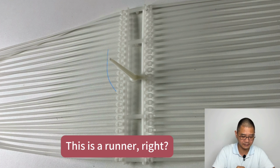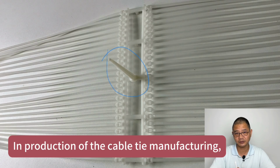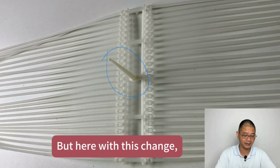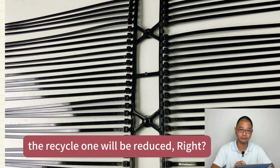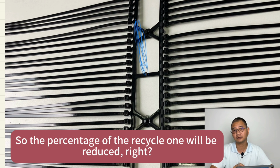This is a runner, and here is without a runner. In cable tie manufacturing, you can crush it and use it again. But with this change, for the hot runner mold, you don't have this runner, so the percentage of the recycled material will be reduced.